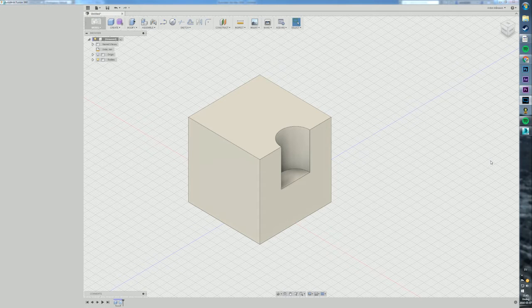Okay, so next up are mesh formats. I'm still in Fusion 360 because I want to show you how it looks when you convert a solid or a surface model into a polygon model. Usually you see polygon or triangle models from, for example, Thingiverse, where people create their models and then export into STL file format, which they upload to Thingiverse. In the best of worlds, people would export solids and parametric models as well to have within Thingiverse to help you reconfigure or redesign the model.